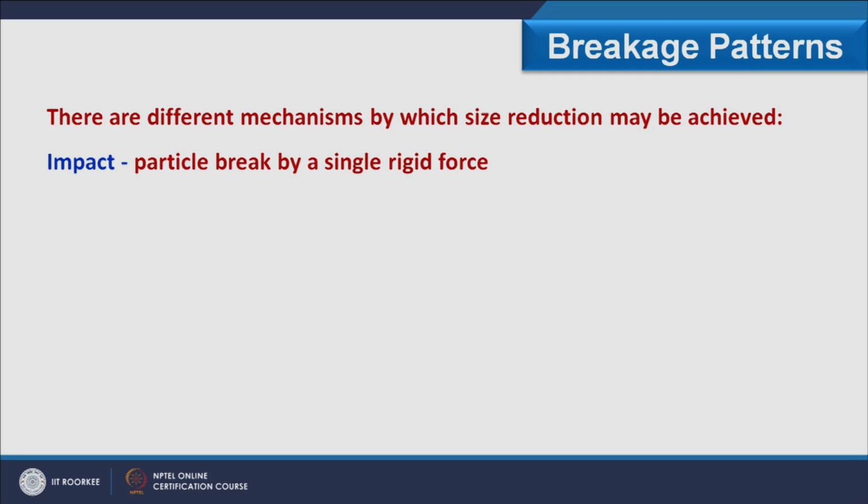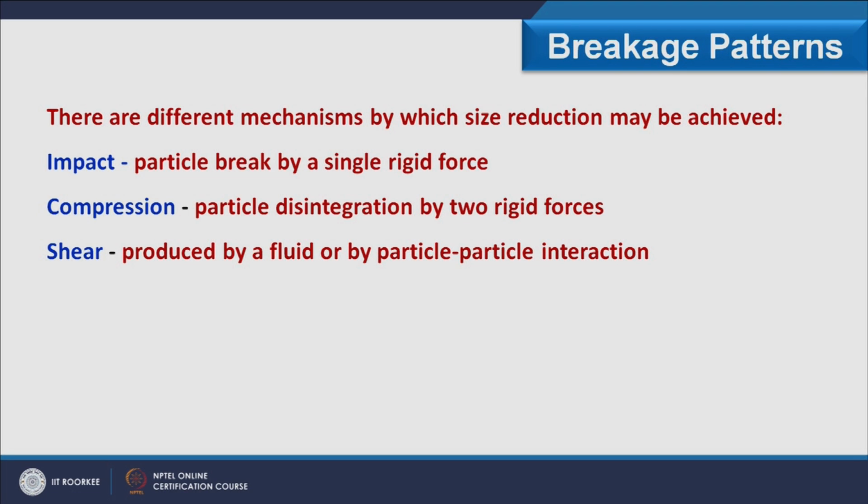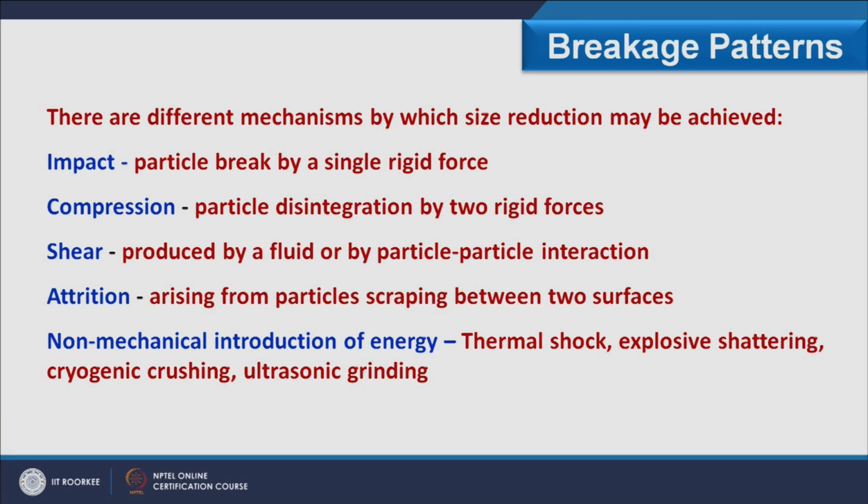Breakage patterns we will discuss here. We have already discussed these during the introduction of size reduction, but these equipment will utilize these patterns, so we are revising them here also. The first is impact. You understand this very well, that particles break by a single rigid force. Second is compression, particle disintegration by two rigid forces. Third is shear, produced by fluid or by particle-particle interaction. Fourth, attrition, arising from particles scraping or rubbing between two surfaces. And another is non-mechanical introduction of energy, in which thermal shock, explosive shattering, cryogenic crushing and ultrasonic grinding are used to crush the material.